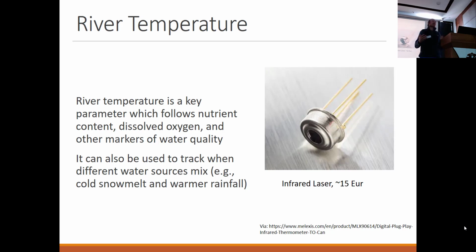It's the same exact principle, and probably actually the same exact chip that they're putting in those thermometers. I'm just taking it out and interfacing it with one of my Arduinos. So that allows me to get a temperature at one particular spot rather than a whole grid. And this is certainly easier to work with and less error prone than this one that's trying to capture a whole grid, which is why we tried both.